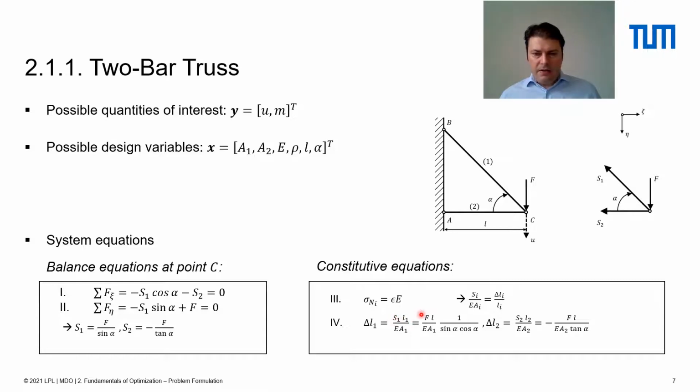And to use F, what we did is we plugged this expression here into this formula. So this way we can relate the extension of those rods directly to the force acting on the node C.